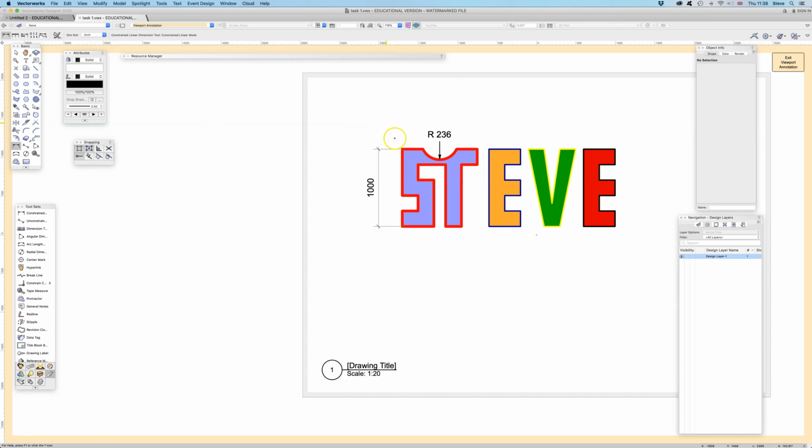So the standard one I used first, I'll just go over that again. The Z key is sometimes quite useful. If I click the Z key, you can see I get a zoom in on the corner, and then I click the Z key again, and then click. So it allows me to get a temporary zoom into corners without having to zoom in and out of my drawing using the zoom function. So that can be really useful. So it was click, click, move out, and then place. So the mouse move was to define this distance here, sorry.